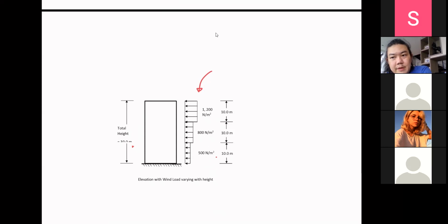But now there is a more complicated and better method to calculate the wind load. They give you equations to calculate the wind pressure acting on the building, and the equation accounts for many realistic factors, such as the location of your building and the terrain.